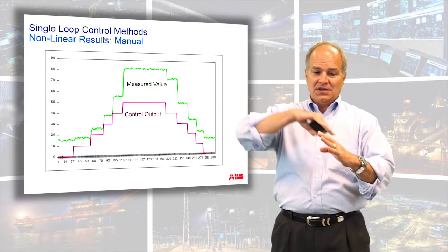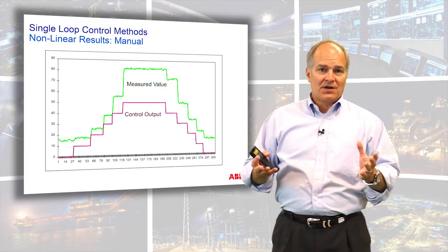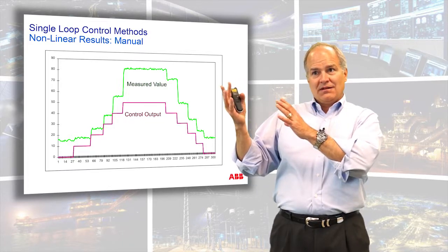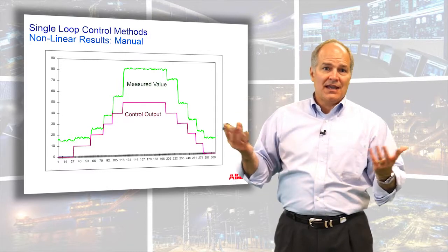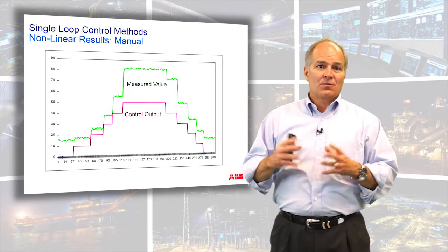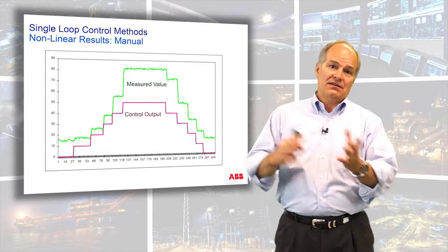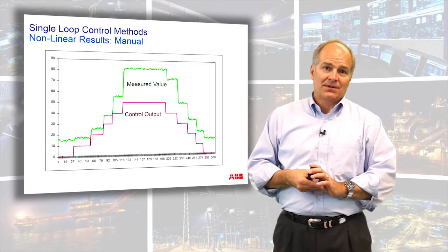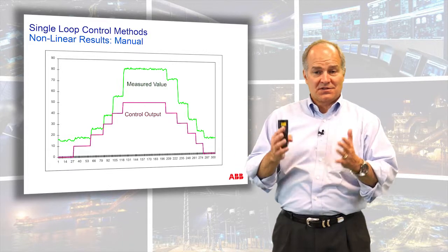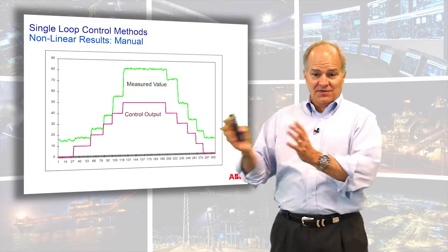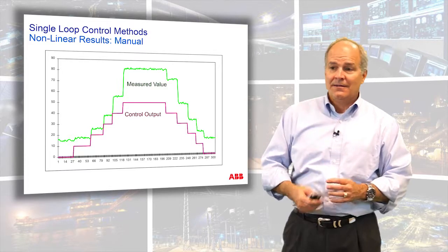I've been to a place where on some particular runs, they ran the valve at 70%. Other ones, they ran it at 50%. When I did a bump test in both cases, the gain was 10 times different. So there wasn't a number that would fit the entire operating range of that particular process. So we came up with adaptive control that looked at the valve position. Said, oh, well, if you're up here, use these tuning numbers. If you're down here, use these, and it worked fine.